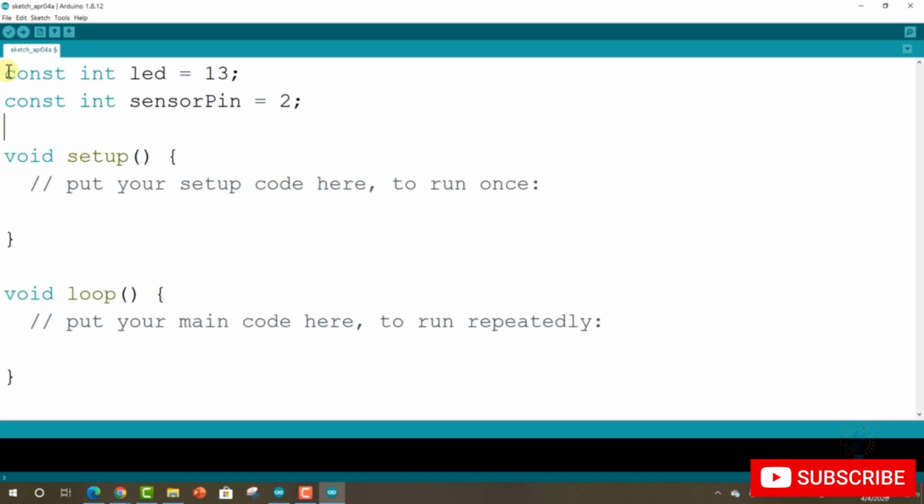Now we need to wait for the sensor to calibrate. So we have to wait between 20 and 60 seconds according to the motion detector sensor datasheet. 60 seconds in milliseconds equals 60,000. So we will have to write this down in our code, but this is like a quick info about it.